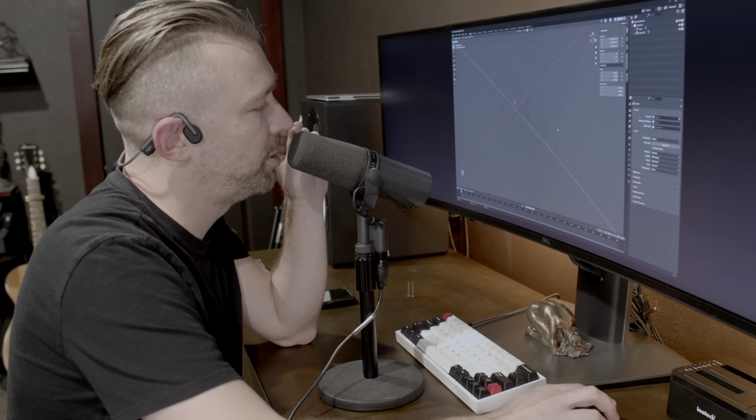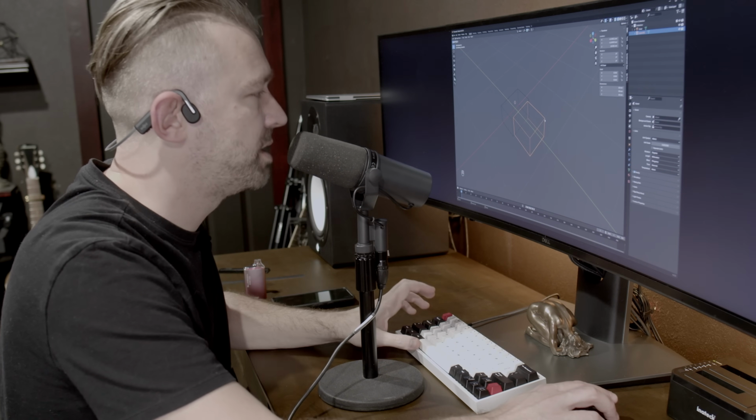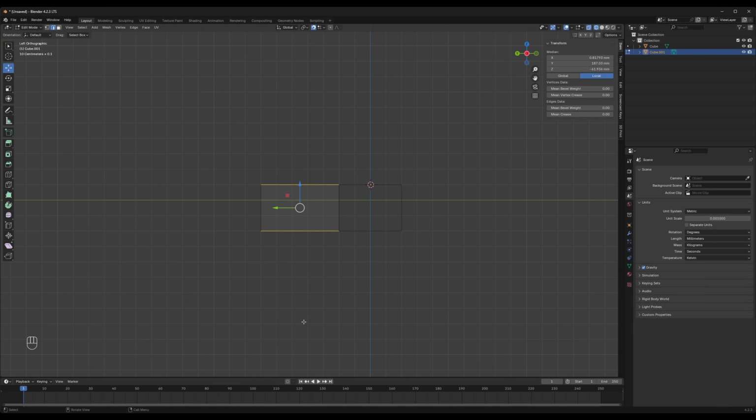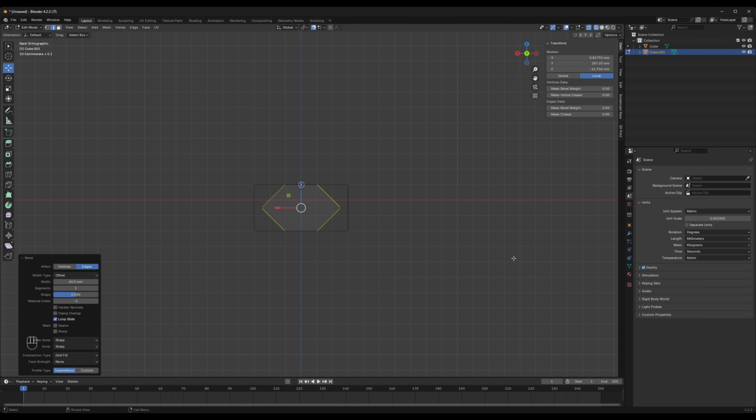For the section that's going to be holding our headphones, what we want to do is click that object and once again go in edit mode. Once we're in edit mode, we can switch to our x-axis and grab all 4 sides of that cube simultaneously. Then we can go over to Y, and once we're at Y, we'll hit Control B to go into Bevel. And at this point, we can just simply move the mouse to move the corners of those bevels. And I want to put that right about here.